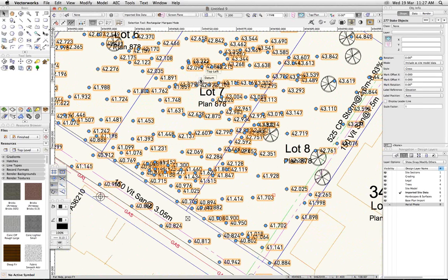And if you got that order wrong, the northings, eastings versus eastings, northings, you'll find that your data and the shape of your site is all rotated 90 degrees. And that's usually your clue to just get out of that, go back, do it again, and reverse the choice in the dialog box.